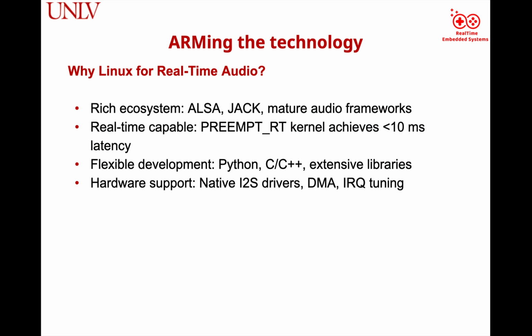It also supports real-time audio under the RT kernel, to achieve below 10 millisecond latency, and it's flexible for developing using Python and C++, and offers built-in I2S driver and DMA support.